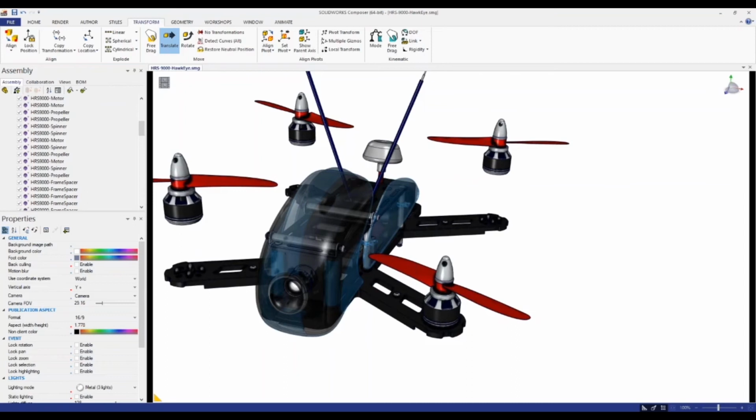One thing to keep in mind too is other situations would be if you're bringing in a component that's maybe not part of the assembly, and then it's inserted. It has a neutral position. So what you can do is specify using the set as neutral properties. For example, being able to specify this location as its neutral property. So if I were to click neutral property, it would still maintain that same location. Okay. So there would be other situations where it would call for that.